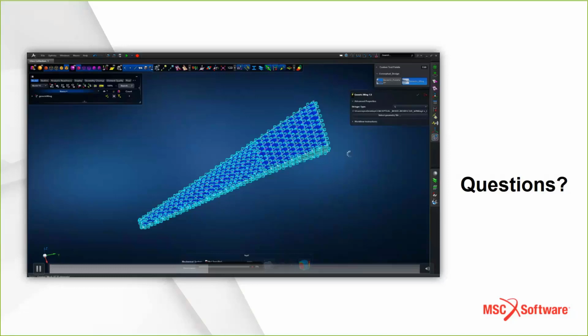Another question is, can we pre-process solution 200 in MSC Apex? Not today. Apex supports 101, 103, 105, and 111. But you could easily set up optimization outside of Apex. You could even set up optimization with a script. When you export the bulk data file, Apex can trigger a script that will then modify that file if you want. So you could either do it via a script that you wrote in Apex, or you could do it outside of Apex, perhaps in Patran or another tool.